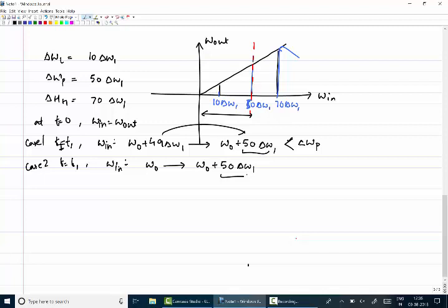Normally when we look at the pull-in range and hold-in range, we do not generally use these small steps. I use the small steps here because if I give a frequency error less than the pull-in range, like this large step, the PLL is able to acquire.